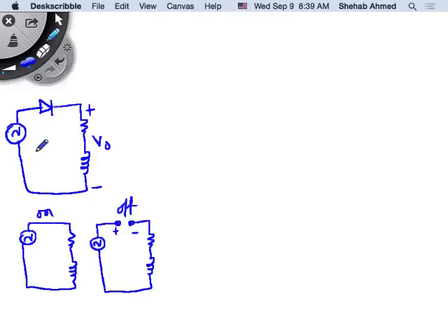That's why you will sometimes hear people refer to power electronics courses as switch mode power supply courses. These power electronics circuits operate in different modes. They switch between mode 1 and mode 2. This is a simple circuit that just had two modes. Some circuits have a lot more modes, depending on the complexity of the circuit. But this is where the switch mode comes from.